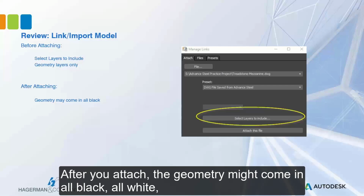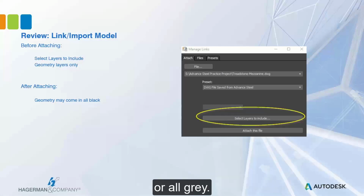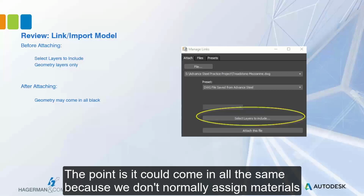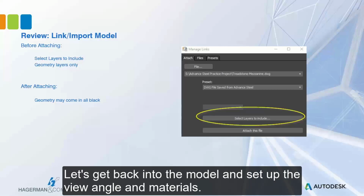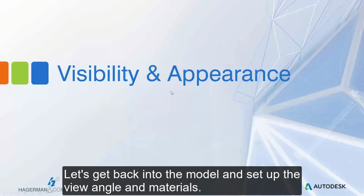Exclude everything else. After you attach, your geometry might come in all black. That's expected. Or it might come in all white or all gray. Point is, it will come in all the same because we don't normally assign materials to our 3D solids in products like Advanced Steel or AutoCAD, and that's okay. Now, that's going to be part of this workflow. We'll look at that next. Okay, so let's get back in our model and we'll set up our view angle and update the materials.